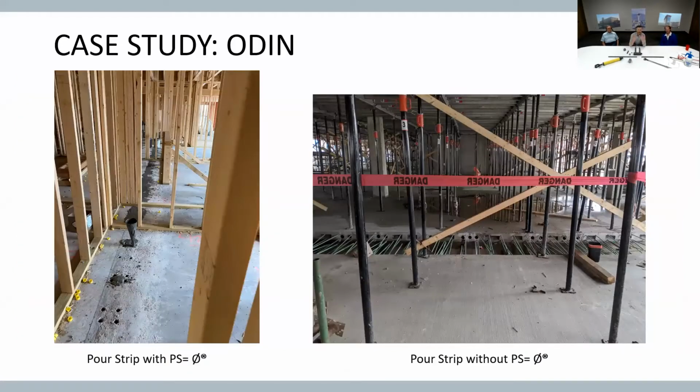So, this is what you get. On the left-hand side, that's our pour strip. And that gap is really small because they didn't pour that other slab until maybe a month or two later. So all the shrinkage and compression on the right-hand side, you're going to get from both sides, but one side had a chance to do all that, and then months later the other one went. So it wasn't that big of a gap. But this is the beauty of it, because that's another pour strip on the right in the same project months later. You can see this picture tells a huge story. You can see on the left what you get, and on the right, same project.